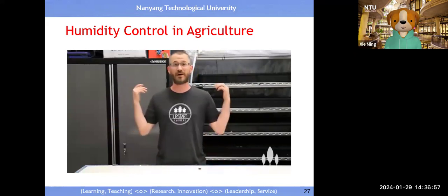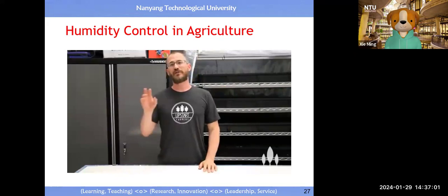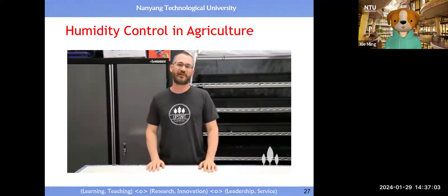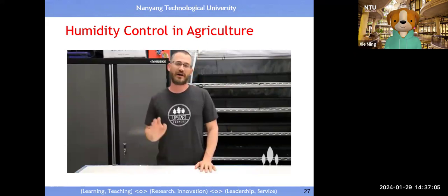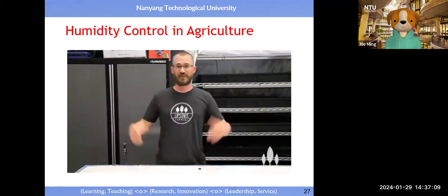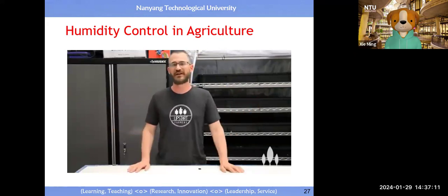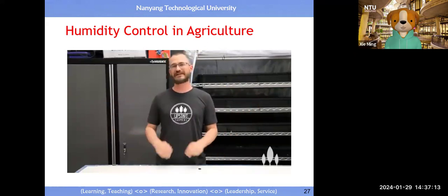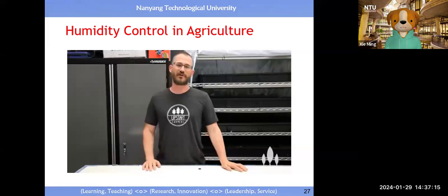So they're just dumping that water into the growing environment. That's usually a good place to start. We also have some humidity calculators and some water vapor calculators on Able for doing CO2-based vapor, basically pounds of water type calculations. That could really help with narrowing down what size of humidifier you need.